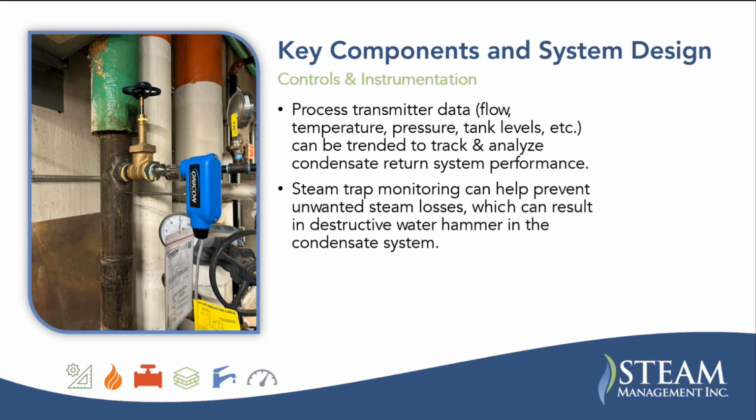And one of the pieces that's often missing is the actual condensate that's making it back to the deaerator. And it's a very useful piece of information for evaluating savings. So this is actually a flow meter that we just recently installed at a hospital. You can see in the picture there, it's not even wired up yet, but this is going to give us some insight into how much condensate they're getting back to their system and the potential for savings on other measures that we're looking to implement.